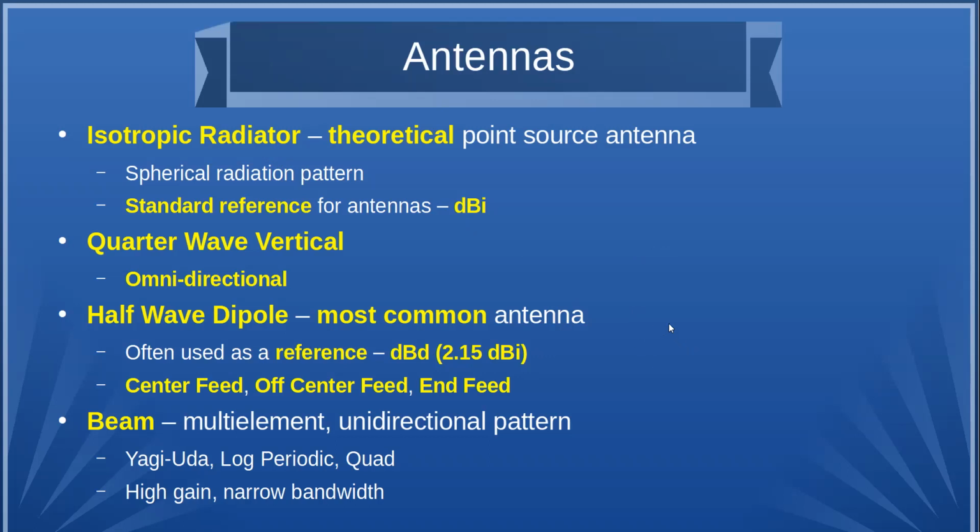Unless, of course, you've got a half-wave dipole in free space, which means miles up in the air. And then it's only 2.15 because there is no ground reflection. But nobody has a half-wave dipole in free space. I didn't realize that the ground reflection gain was that much. That's a lot. I just watched the Dave Castor video on that.